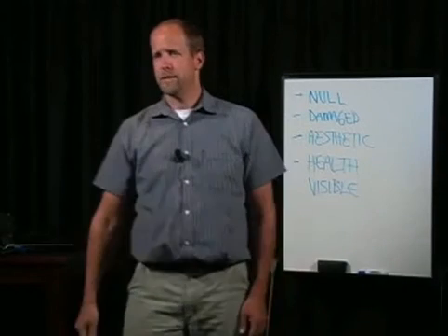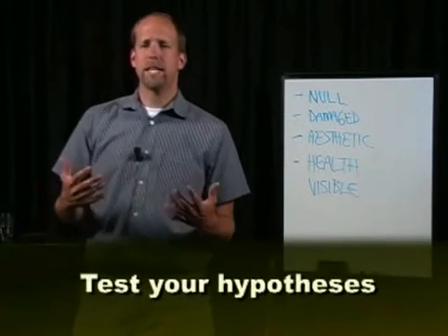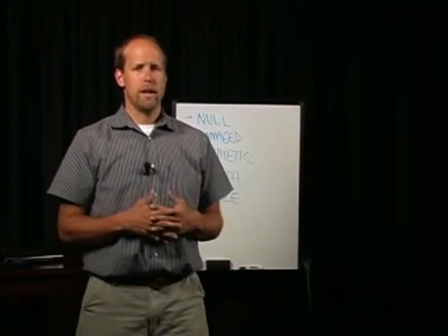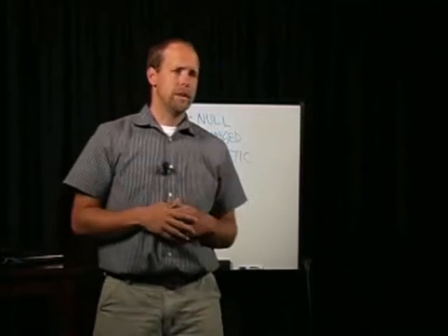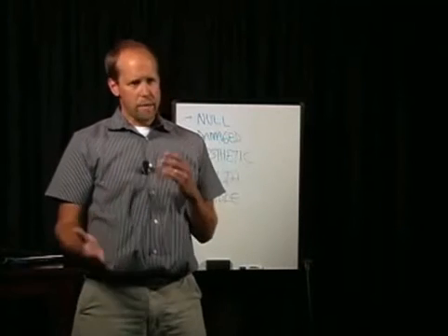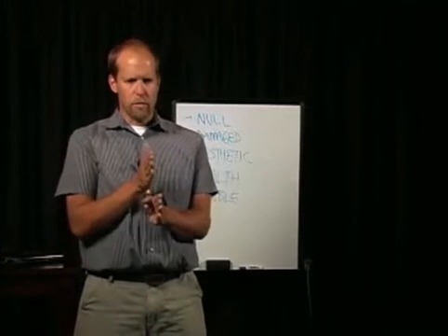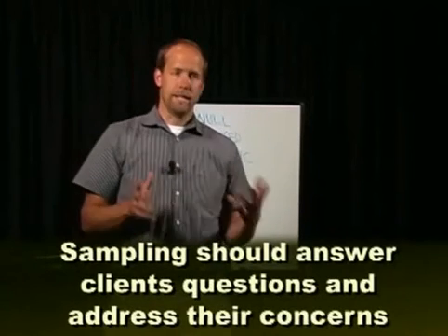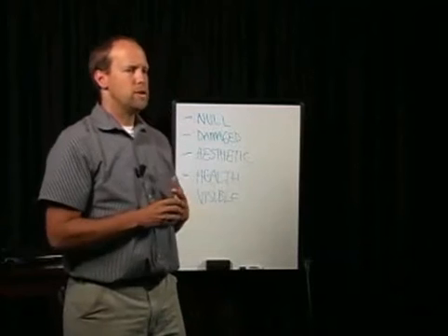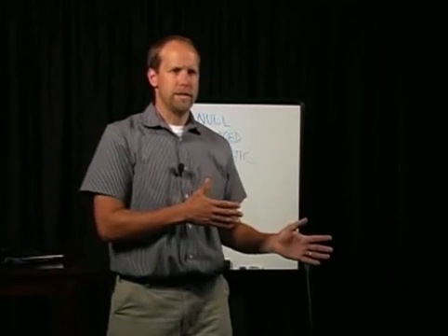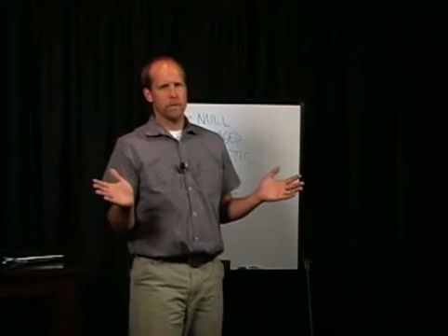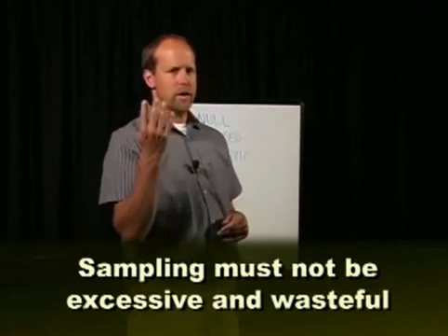Test your hypotheses. Test the hypotheses by collecting and analyzing all relevant information about the building, its systems and components, by performing a non-invasive visual examination and taking multiple mold samples. The mold sampling should be in alignment with the client's concerns about mold. In an attempt to conserve time, money, and resources, the amount, the type, the location of the samples should directly address the hypotheses that have been developed by the inspector and the client. Don't take 1 billion samples and waste your client's money if all you need are 4.